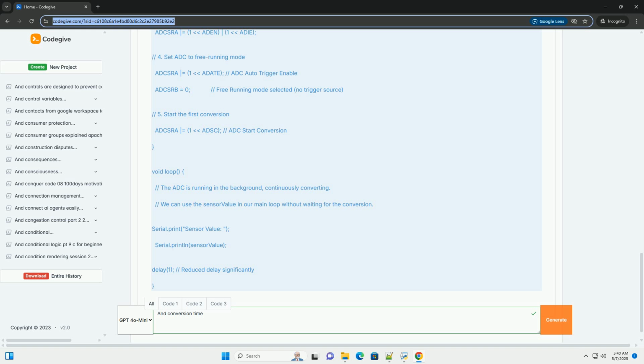5. Troubleshooting ADC issues. Incorrect readings. Noise: use filtering techniques, hardware or software, to reduce noise in the analog signal. Insufficient acquisition time: increase the acquisition delay. Grounding issues: ensure proper grounding to minimize noise and voltage offsets. Reference voltage instability: check the stability of the ADC's reference voltage. Slow conversion rate. Prescaler setting: verify that the ADC clock frequency is within the recommended range. Software overhead: optimize the code to reduce the time spent on ADC related operations. Aliasing: ensure that the sampling rate is at least twice the highest frequency component in the analog signal.